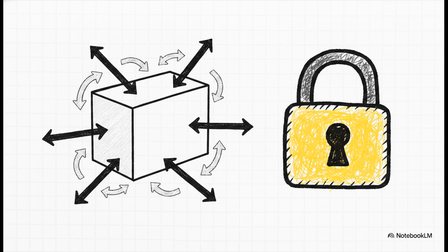If you don't constrain these degrees of freedom properly, well, the datum positions won't be consistently measurable. Your perfectly good parts will suddenly look like complete scrap during measurement, and a lot of time and money will be wasted arguing over inspection reports.